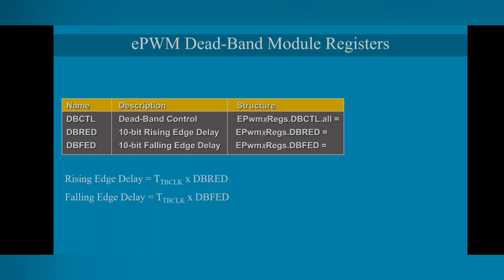So what kind of registers? Now we want to provide the delay during the falling edge and rising edge. How much delay we want to provide is the first thing we need to think about. You can check the delay with the data sheet of whatever IGBT and MOSFET you are using. From the data sheet you can check the fall time and the rise time. With the help of that you can select how much delay you want to provide.